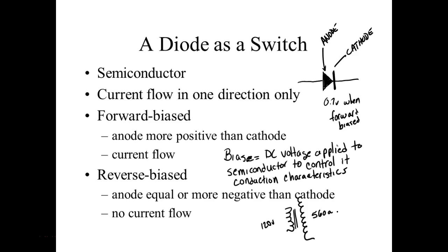Well, the problem is Alabama Power. They're not trying to sell you voltage. They're not trying to sell you current. They're trying to sell you power. Power is work, right? You understand? So if I know power is equal to V times I, then I know I would be equal to P over V. It means the higher I can make that voltage, the less current it's going to require to send you that power.